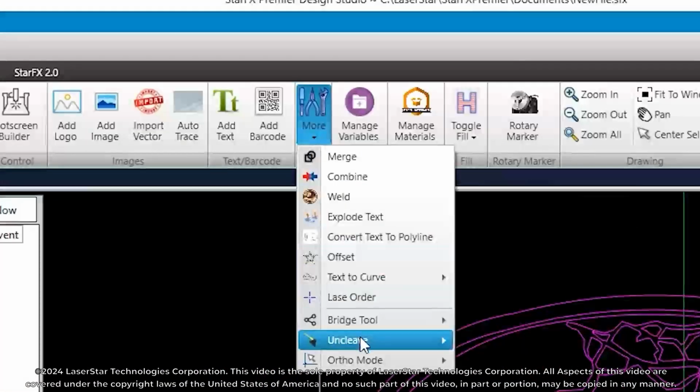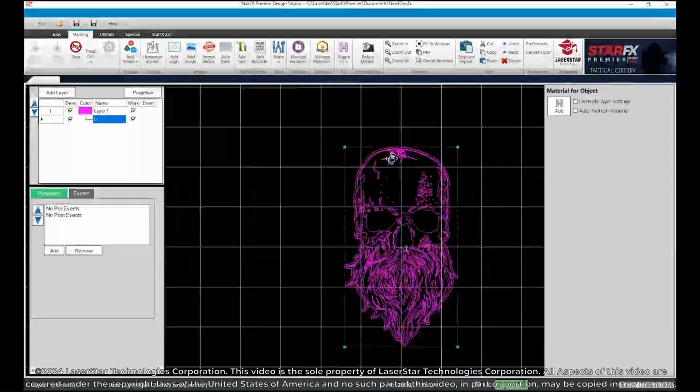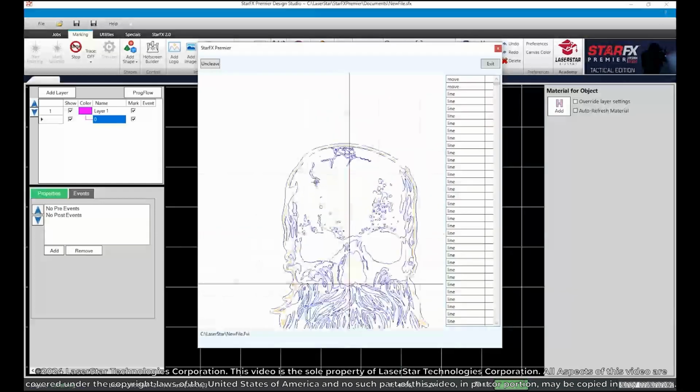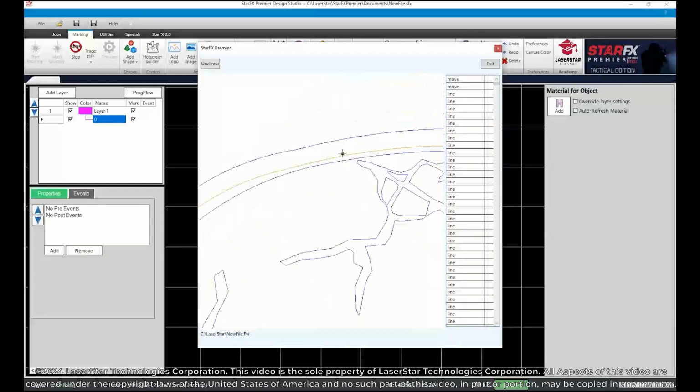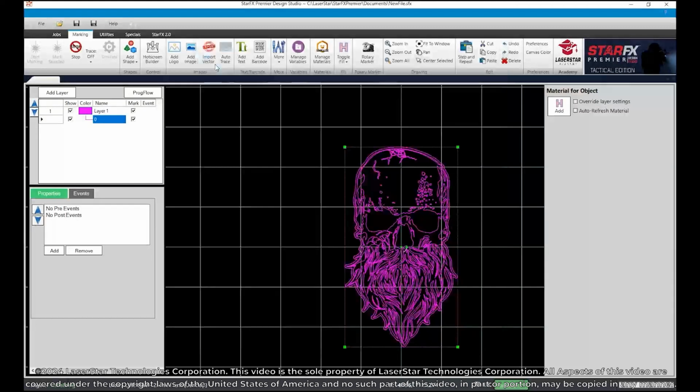The other adjustable parameter is to check the Show Window checkbox. When this is used, a new menu will pop up and show the line segment that has a broken node in red. This will allow a curious user to pinpoint where the break could be and still use the Uncleave function within the menu.